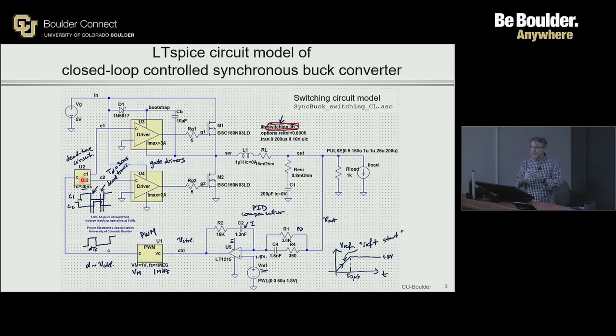Well, if you make the dead times really, really long, you're never going to be turning on the rectifying device. But there is somewhere in between as well. 200 nanoseconds would not be too long with respect to the microsecond we have in the period. But it would still be too long from the practical point of view. Why?